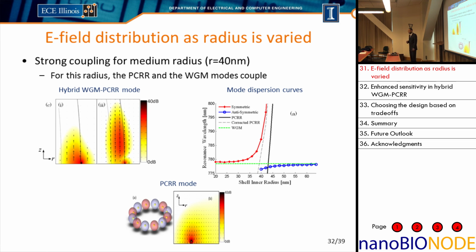It turns out that this is very simply explained as the coupling of two separate resonator systems. One is the whispering gallery mode. The other is the plasmonic chain ring resonator. If you model the plasmonic chain by itself, you can see that it has certain field localization properties that basically confine the field very tightly near the plasmonic chain.